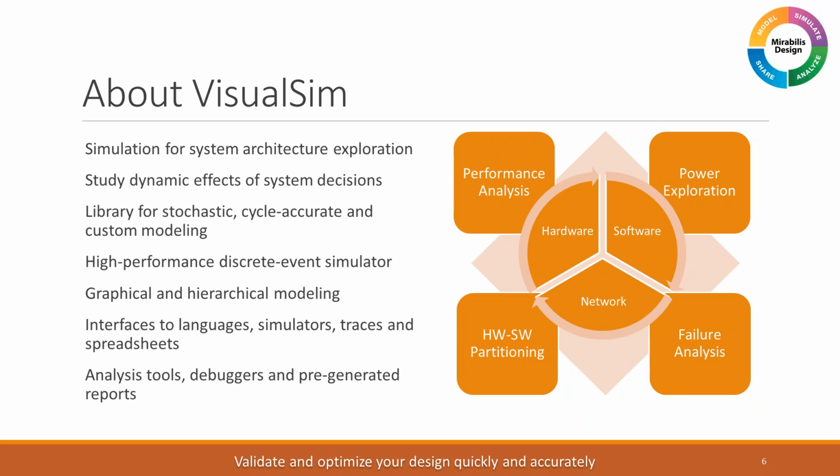Then comes hardware-software partitioning, which is the main purpose of our webinar today. It is about how I can quickly determine which functions or elements of my design need to be moved over to hardware, so that I can free up my core processors to do all the other, more general purpose tasks. That way, I can either reduce the power or improve the performance of my system.